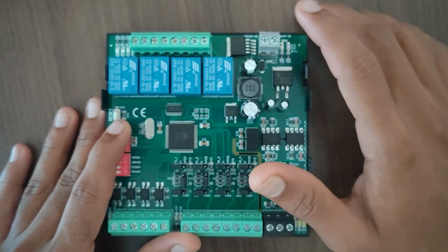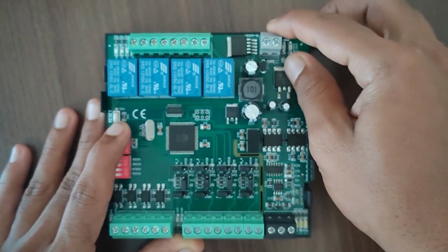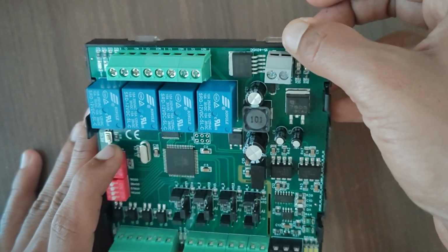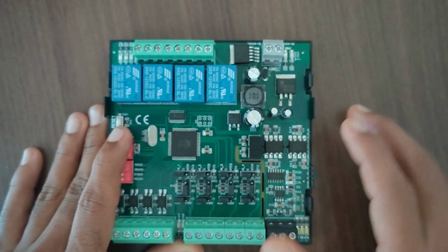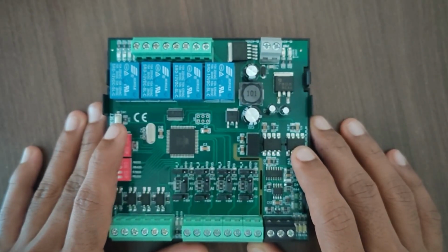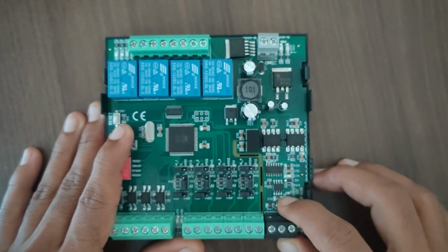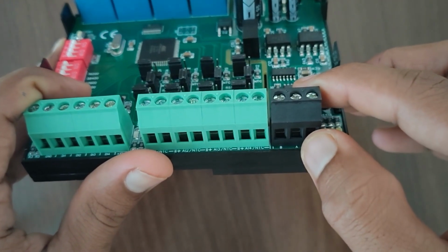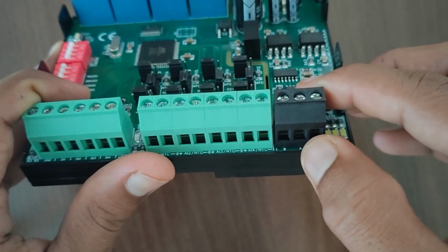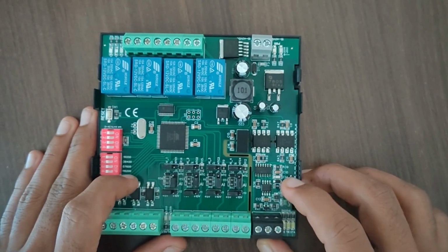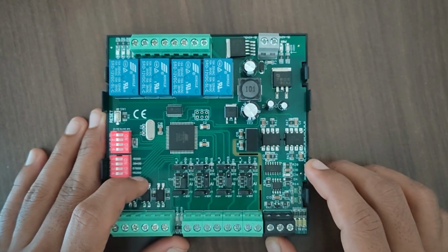In this model, here we have the power connection part. For this power connection, we have the configuration as positive and negative. For the power supply, you can provide up to 24 volt DC. For this board, here we have the RS485 for communication. Here we have the configuration for the connection, A for the positive, B for the negative. We can connect with the Modbus cable, that is the RS485 cable, with the PC to get the data.